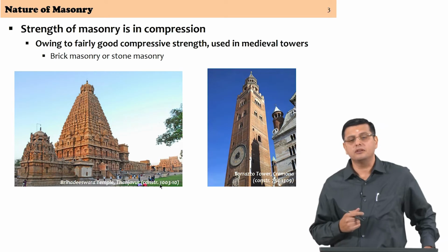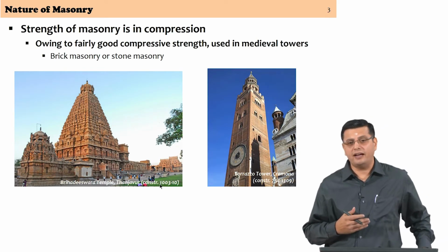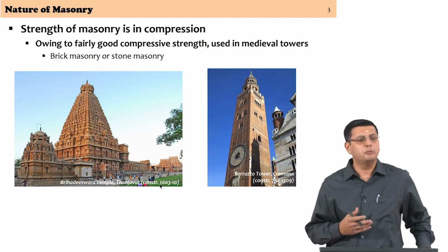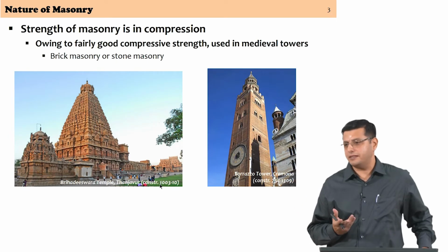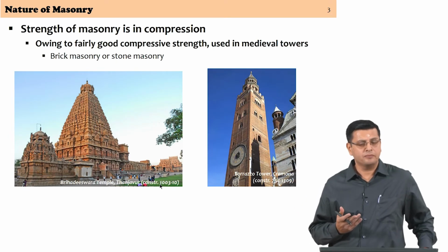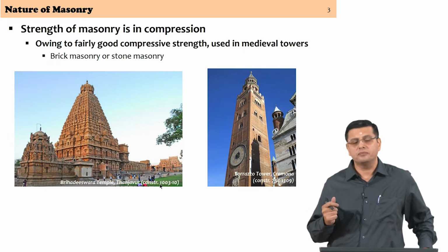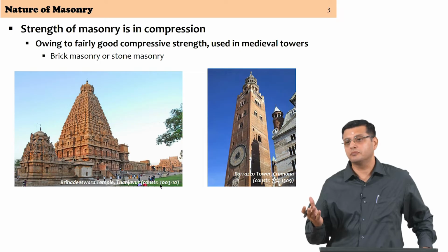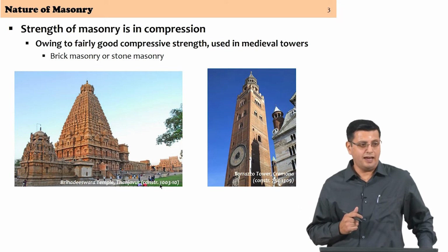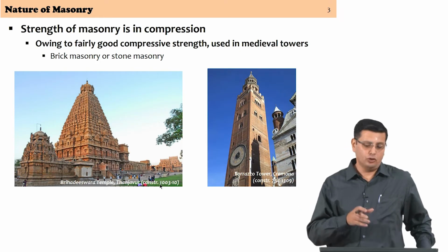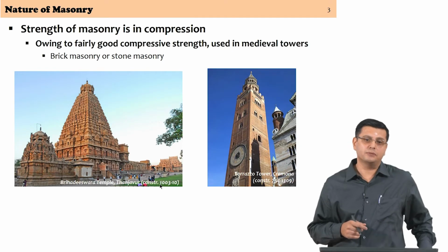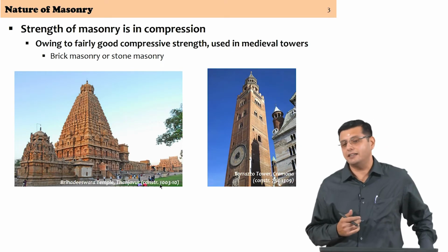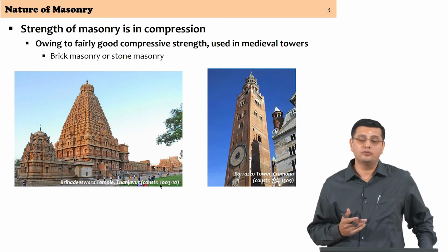Masonry units, you will see in the next week that we have a different classification for their strengths, but 5 megapascal or 5 Newton per millimeter square or a 10 Newton per millimeter square is a fairly good estimate of the strength of bricks that are predominantly available. You will see that if you assume a nominal strength for the brick and look at a brick that is about 19 centimeters by 9 centimeters, the stack can easily go for a few kilometers.